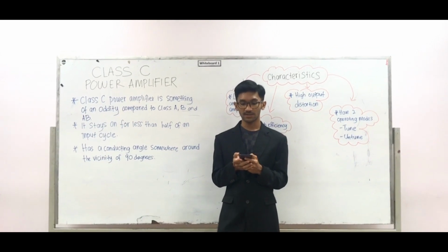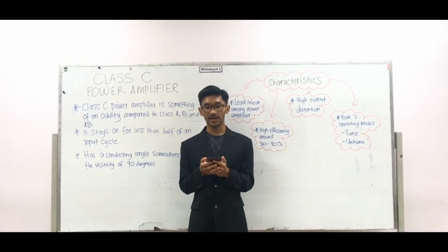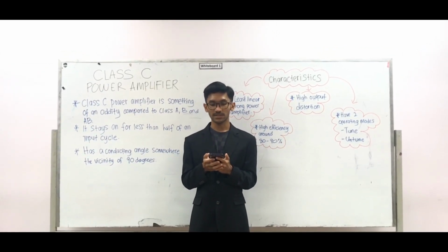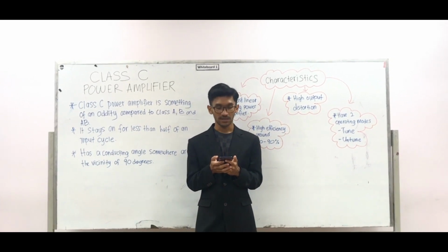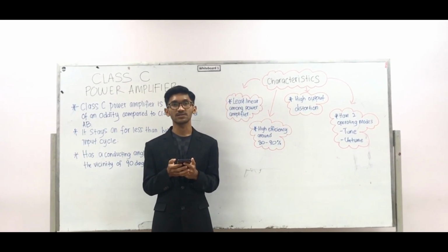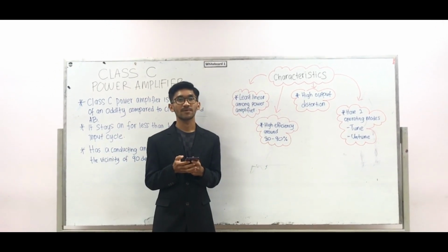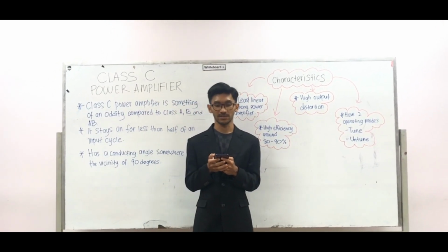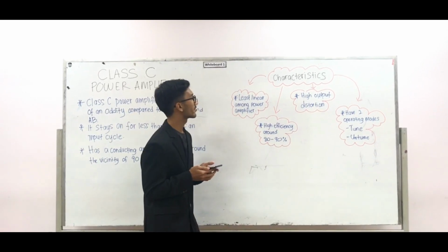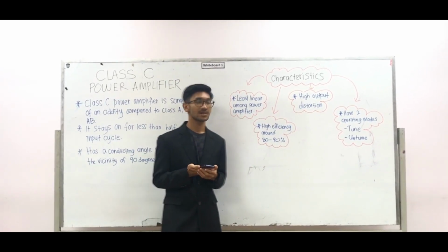Class C also results in high efficiency, but also causes high distortion in the output signal. So Class C amplifiers are usually not used as audio amplifiers. We use Class A power amplifiers for audio amplifiers. Okay, next we go for the characteristics of the Class C power amplifier.